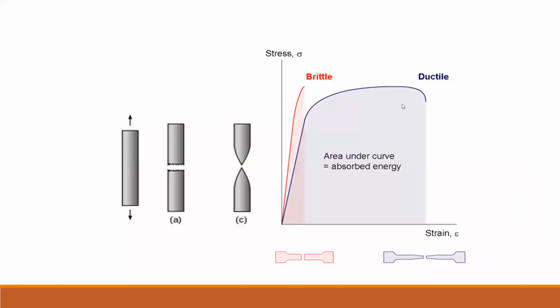Here you can clearly understand what ductility is, what a ductile material and a brittle material are. Here you can see a ductile fracture and a brittle fracture. This is a component, and we are going to apply a tensile load on it. Before applying the tensile load, I'm measuring its length, which is called the initial length, say Li.